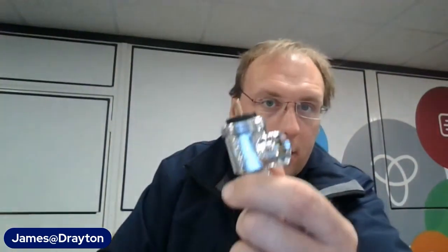If somebody wants to remove the radiator for decorating, they'll take the TRV head off, they'll put a decorator cap on here, wind the lock shield all the way down, radiator off. When it goes back on, all they've got to do is wide open with the lock shield, decorator cap off, and the sensing head back on, and they haven't lost balance. So it's a really good idea if you're using these to do the balancing on these.